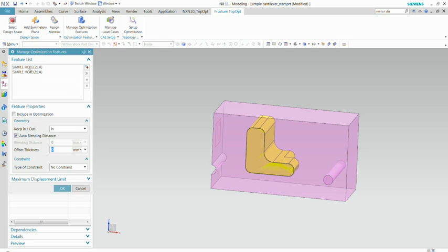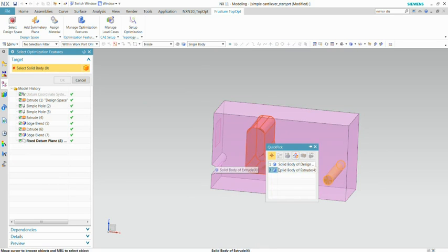Further on, we're going to say that around that central hole that you see highlighted over there on the left, we want at least 1 millimeter of material. For example, that we want a full zone for an axis. And at that location, the part is also fixed, so that the part cannot move around that hole. We're also going to define an offset around the right hand hole. And finally, I'm also going to add the shape in the middle, the yellow one.